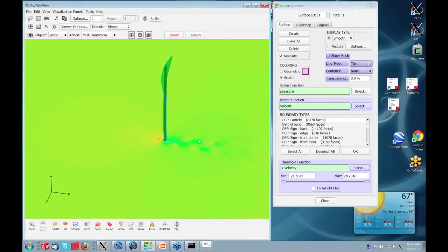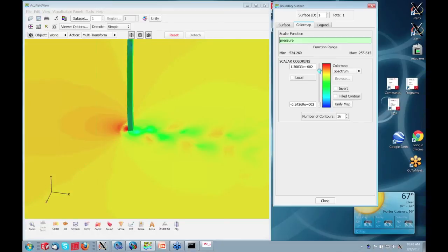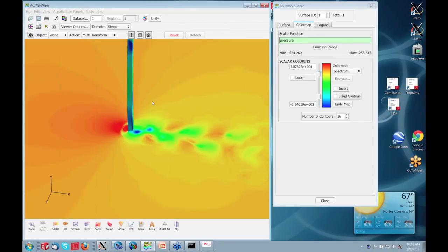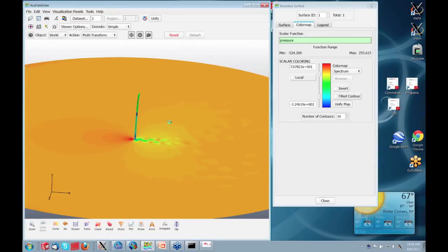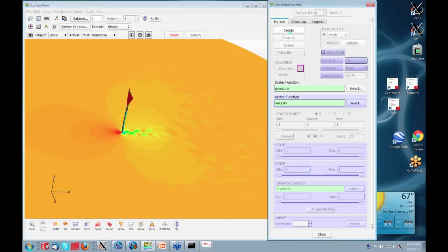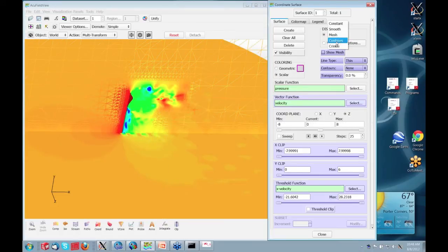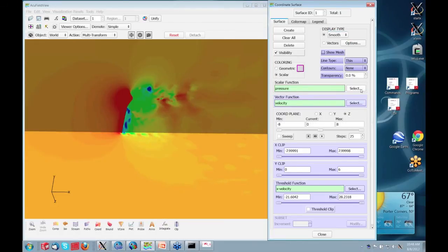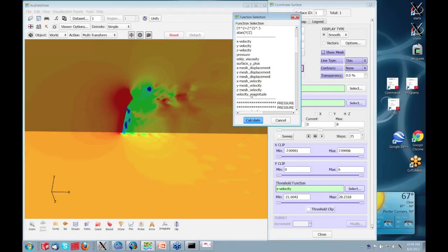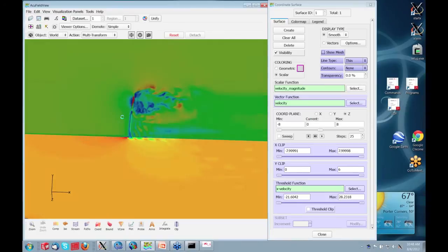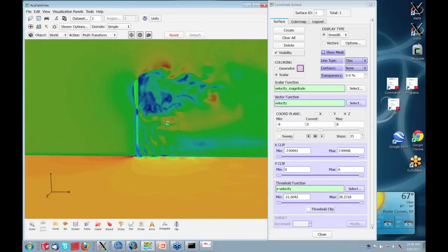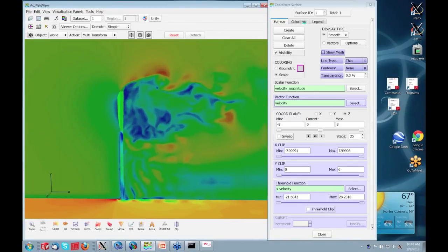And you can also see the pressure imprint on the ground here, indicating that we have a lot of transient flow present. So it appears that we have some vortex shedding present. And if I draw a cut plane in the z direction, and I color it by the velocity magnitude, we'll see very clear indication that we have a highly transient flow here with a lot of vortex structure present in the wake.